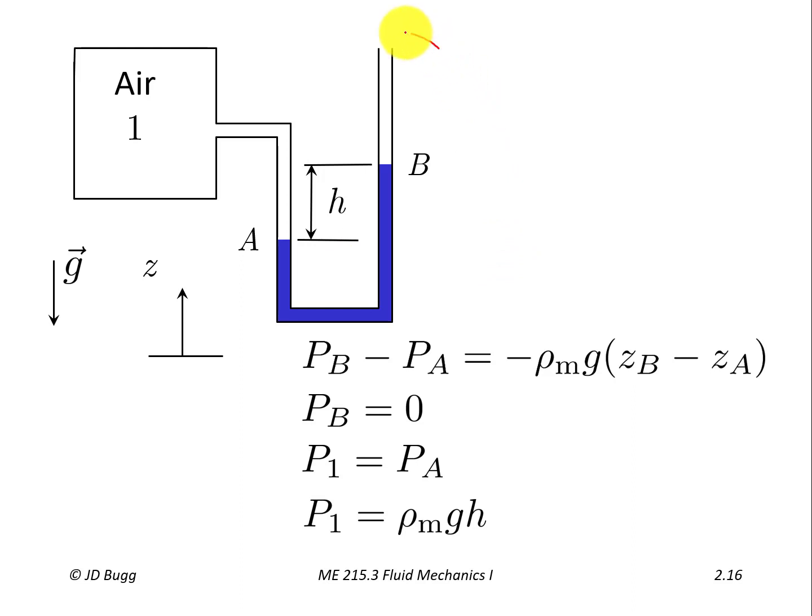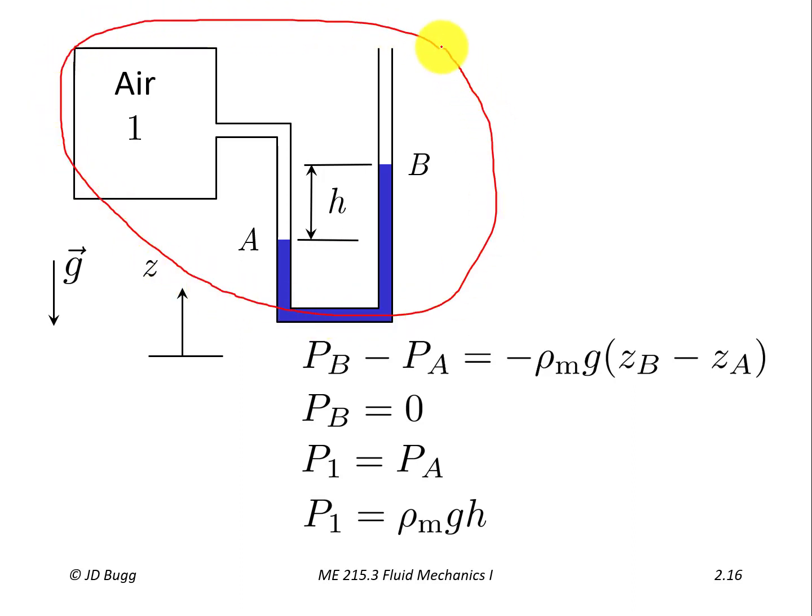So, like I said, in the first lab in the course, you're going to see basic manometers that look like this, and you're going to see a couple of variations on this as well. Manometers can be designed in different ways for different purposes. They can be made to be extremely sensitive, and one of the manometers that you'll see in the lab is an inclined manometer, where this measurement leg isn't vertical, but instead it's at an angle. So small pressure changes give relatively large deflections of the manometer fluid along the manometer tube. But you'll see all of those variations on the theme in the lab.